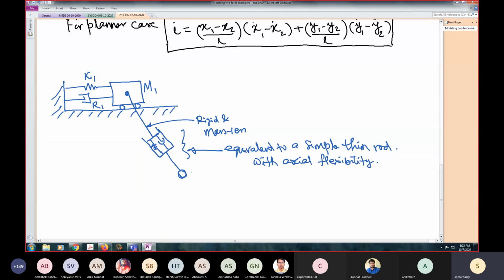Sir, in Hooke's law, the damper is not taken into account, right? Actually the stress is E times epsilon, plus there is another term, lambda times E times epsilon dot. This term is called Rayleigh damping or beta damping. So that damping is there.